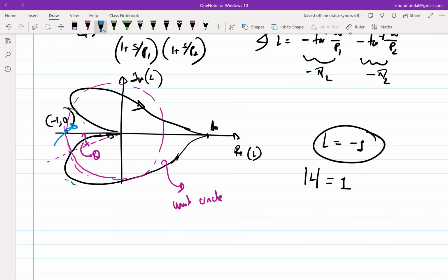And theta equal to negative will mean, right? Theta equal to negative means I have encircled. Theta equal to negative means this is the theta, this becomes the theta, which means I've encircled. So the count of the theta starts in this direction. That is positive theta, which means negative theta means going the other side, which means theta equal to negative means you have landed up into instability. And it also gives you a measure of how much instability, how much away from that unstable point that you are deciding.